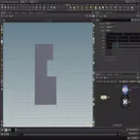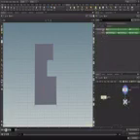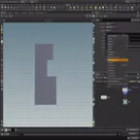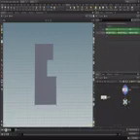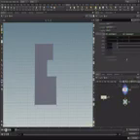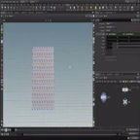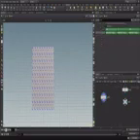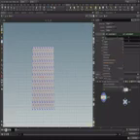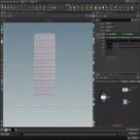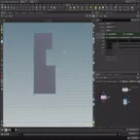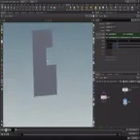So at first, for the grid size, we can select the X direction, do copy parameter and paste it in there. Do the same for the Z direction, paste it in there. There we go. So now it's still a little bit offset, and that's why we need the centroid. So let's copy the centroid and place it in there. And now if we make this gray and we look at this thing, it's already quite far, but it's not completely done yet.